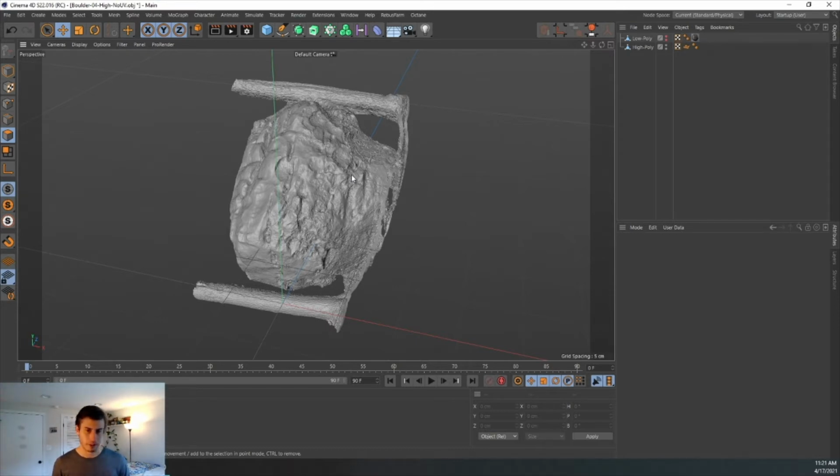Oh man, I'm blanking. I have a whole workflow in ZBrush. That's what I'm looking for. ZBrush, where I actually take the high geometry and bake it down into a lower geometry mesh, and I export all of this high detail into normal maps and displacement maps.